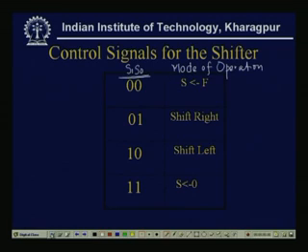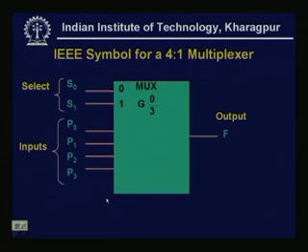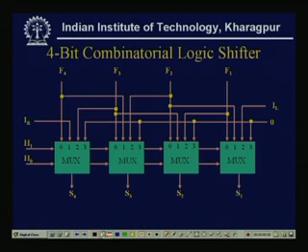Now, we see how the circuit behaves like that. See that H1 H0 is 0, 0. If it is 0, 0, then the first input line, the 0th input, should be passed as the output.